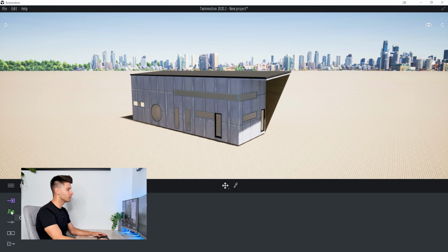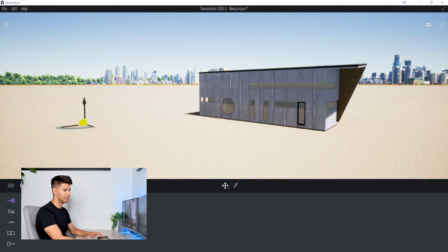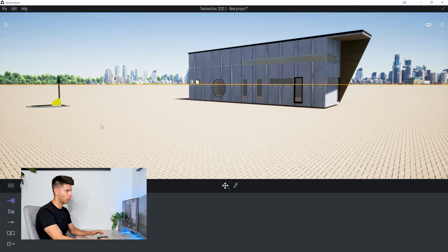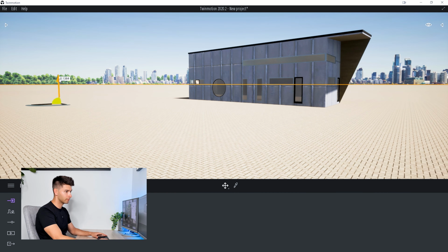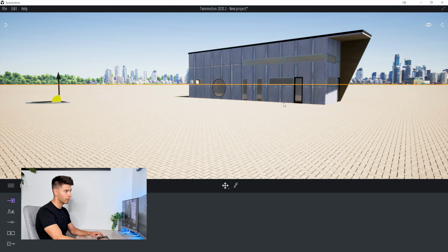So what we actually want to do is start putting some materials, some textures, and making this look nice. Now it's a different control mechanism for Twinmotion as it is on ArchiCAD, but it's similar to that explore mode. So by clicking on this floor plate, we can drag that up to just hide the bottom of that. But because our door is so much higher, we're going to keep dragging it to the bottom of the door.